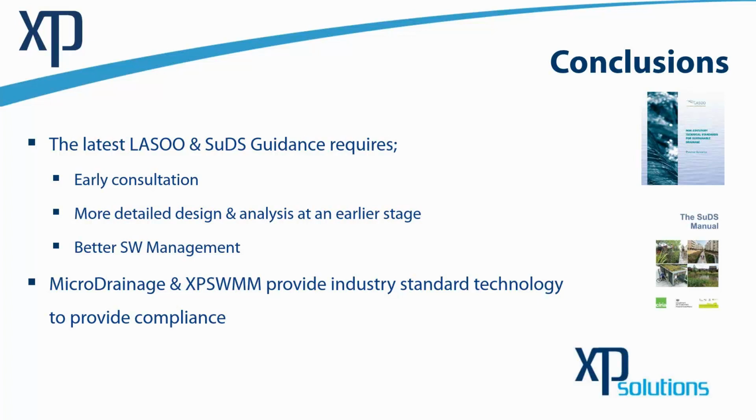Yeah, soil saturation. And in terms of the hydrological methods that you can use, there are many hydrological methods that we could incorporate. The latest one, if we're looking at that kind of scenario, would be RefH2, where the ground, if it was to be farmland, becomes increasingly saturated throughout the event. That's taken into consideration as well. So we run FSR, FEH, RefH2, as well as a lot of different hydrological methods that are used in the US, Australia and the Middle East, etc.